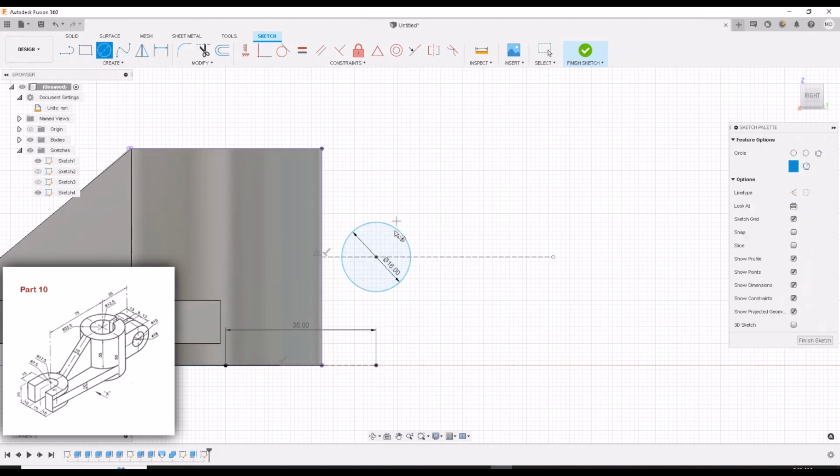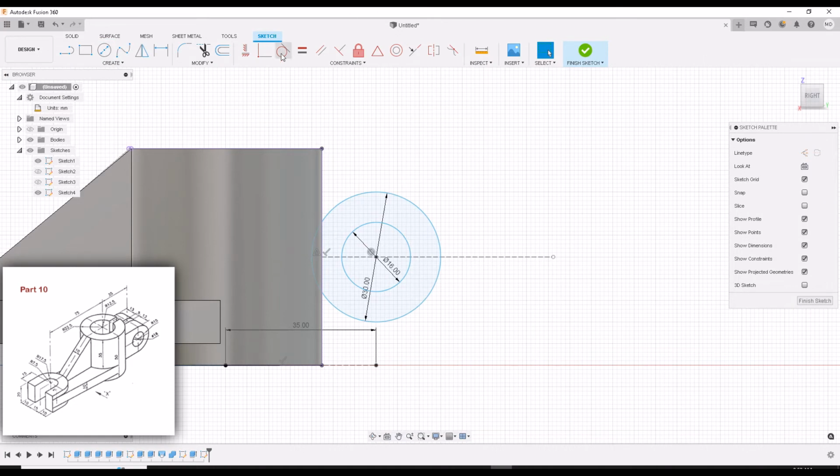Now we want to do that again since we found our intersection, but this time it calls for a radius of 15, which is a diameter of 30. Okay, good. Now press enter. After that, trim away. Let's do some trimming. Now we have to create a line segment that goes from the tangent of this OD over to this part here, because we have to extrude. So let's drag. Just like before, we want to do the same thing we did before. There it is. Let's trim away.